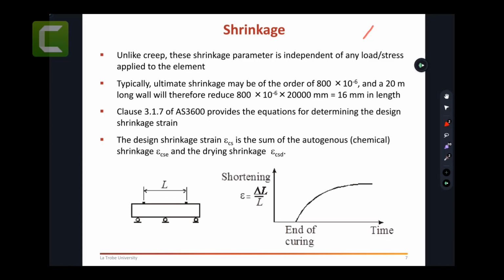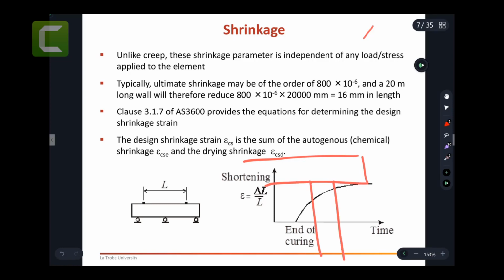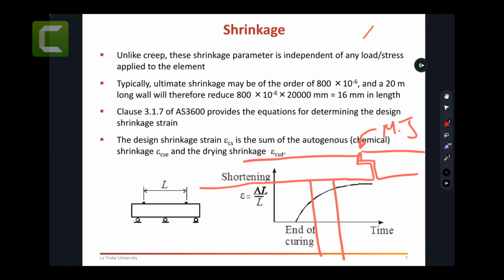Okay, and while we're there, so if you have a slab and this is the column, you have to stop it and you can create a corbel. What does corbel mean? A movement joint, like it's just going to stop like that with a step, and then your next slab will come on top like this. So this is why I'm calling it a movement joint. This is a suspended slab because we cannot just do a saw cut from the top, right? We have to do a movement joint.